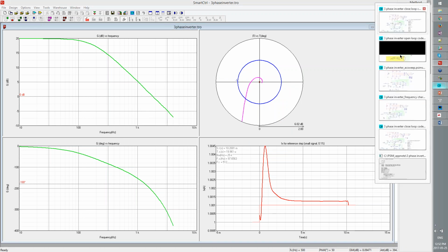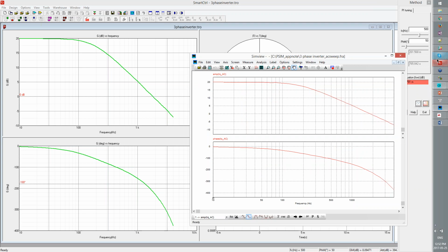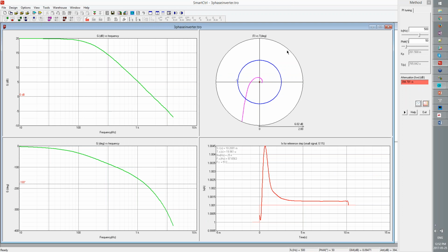So I've not done the math on so the sweep. I think I know what you're asking. The sweep response, so this is IQ perturbation versus IQ feedback. So this is introducing a perturbation in IQ and observing the resulting perturbation. So IQ versus IQ. We could look at coupling as well if we wanted to: IQ perturbing IQ and looking at ID, and perturbing ID and looking at IQ. So all of those, the interchangeability is considered, but in this particular instance, I'm treating ID and IQ as separate control signals.